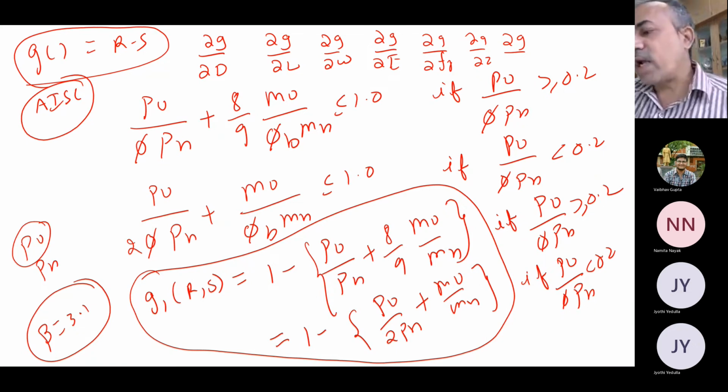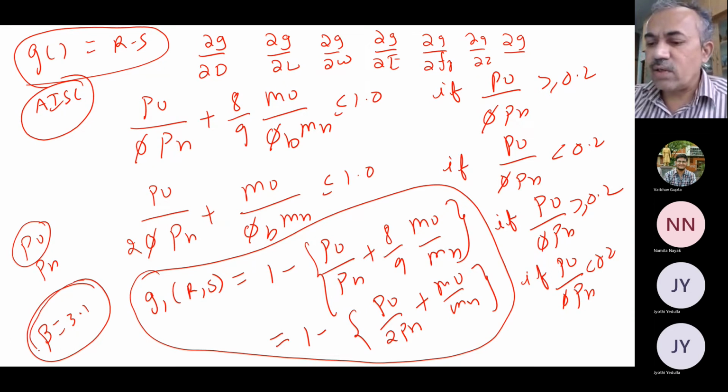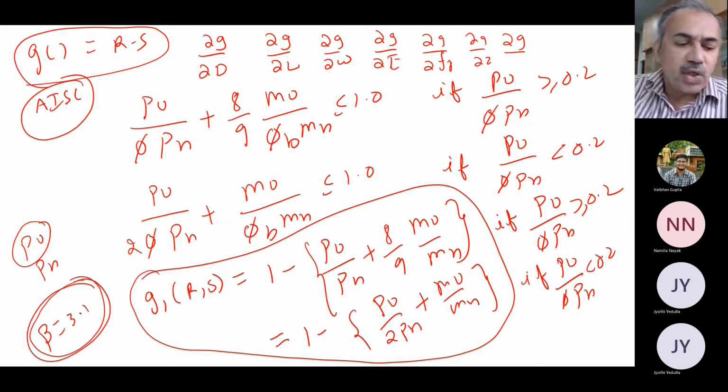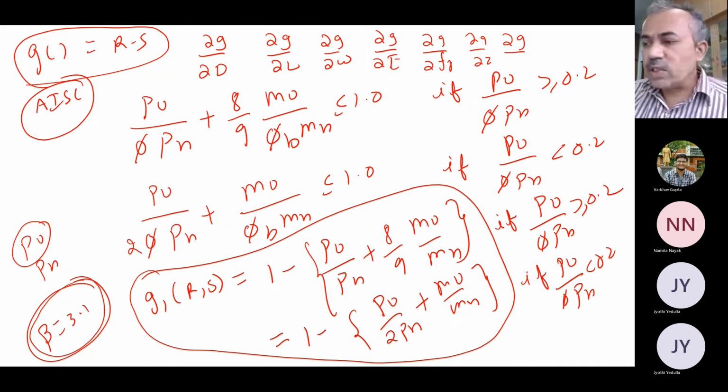And you get convergence, and of course whatever you use, the reliability index should be more or less close to 3.1. So please try. This is for the steel, this one you can just try with your MATLAB. So fine, with this, this is how you can do the stochastic FEM for linear static problems. It is a simple way you can try here.